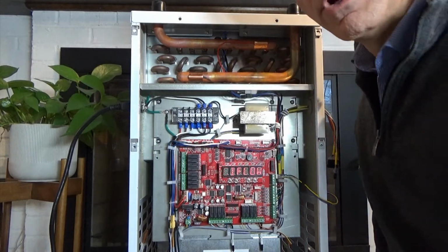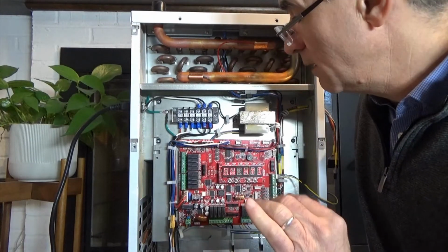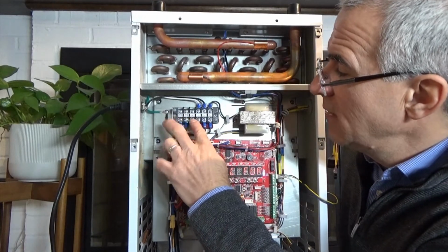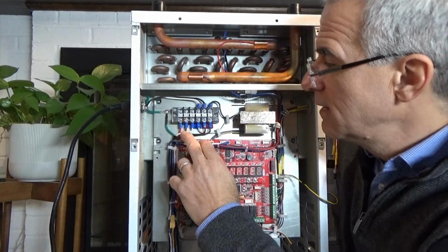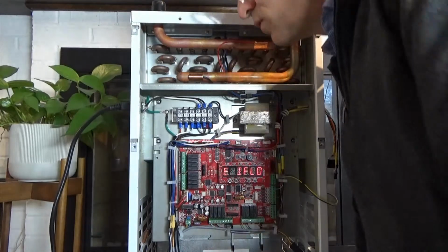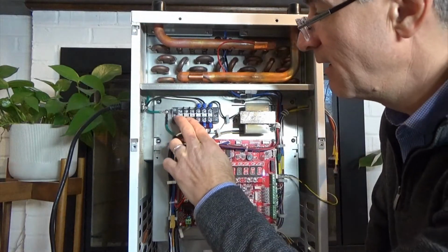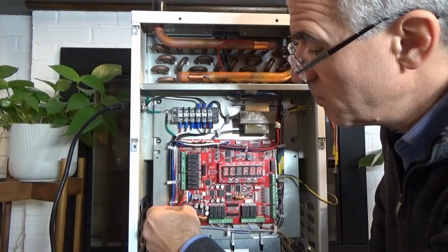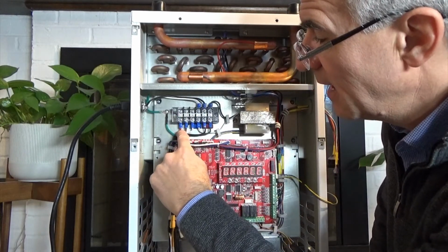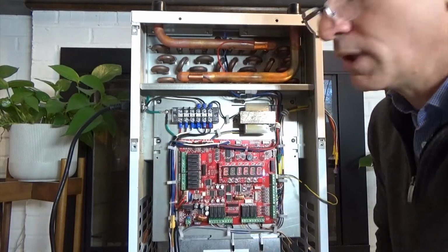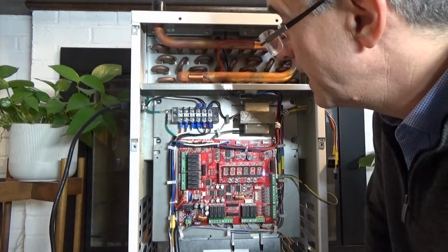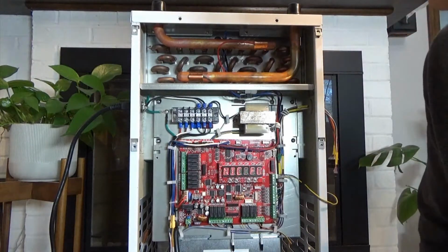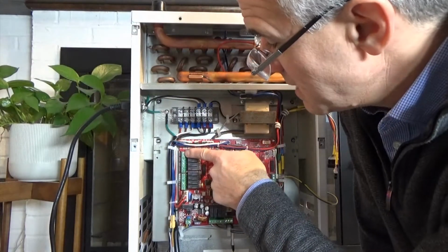The secondary pump, or the pump that's bringing the water into the iFLOW, will connect to this C1 and N contact. So the C1 will be the hot and the N will be the neutral for that pump. We're supplying the variable speed pump control from this red colored wire that's supplying C1. So just to give you a look at that, we'll bring back the computer, but so that's the circulator.